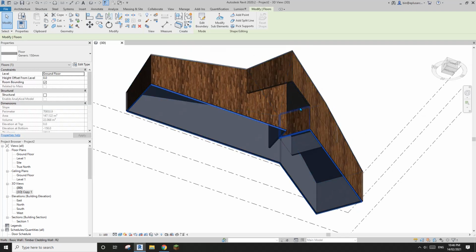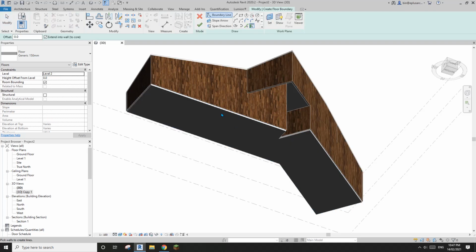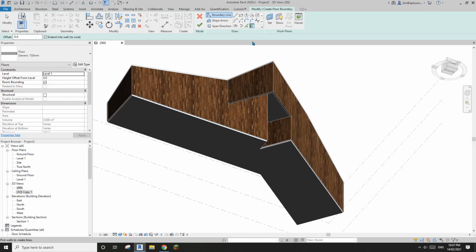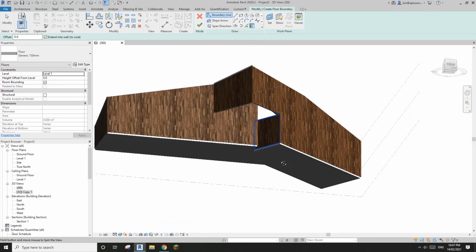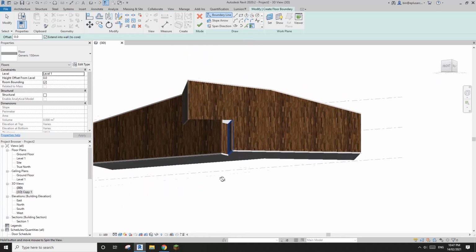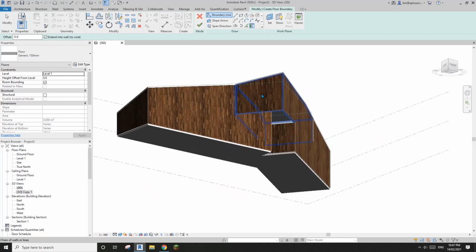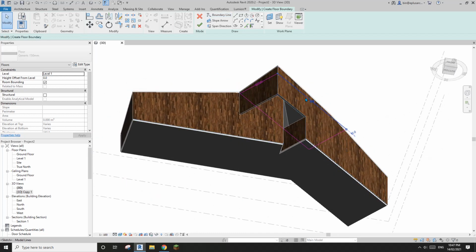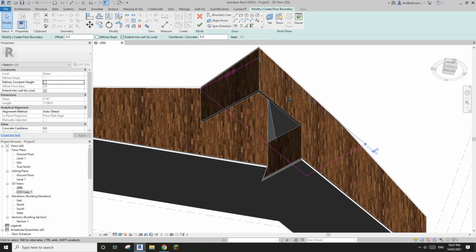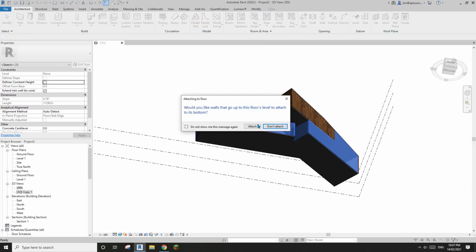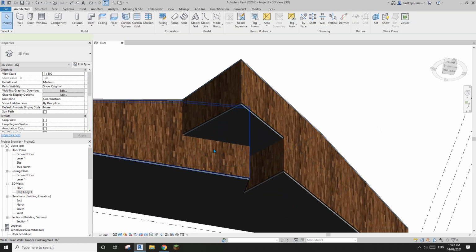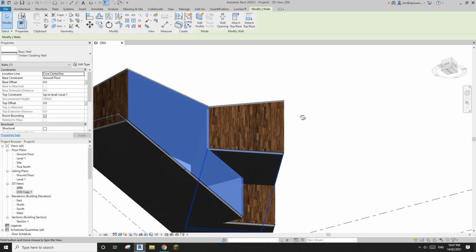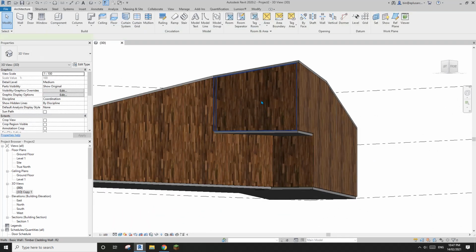So then let's do the upper floor. Okay, select this floor, CS, create similar, change the level to level 1, pick wall. Let's have a look where the upper floor wall is. I'll just try tab. Okay, tab, see, that's it. And also exterior face. And okay, so don't touch. I will let Revit know if I need to. So let's have a look over here.